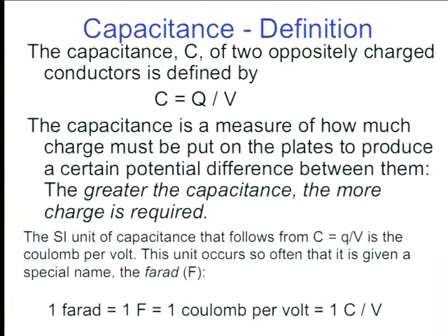So what happens is that if you plot the current, what you really have to do is put a resistor in here to make things act well. The current is going to start at some height, and let's say you have a switch in here, which I will show you in a minute. The current starts, and over a long time, eventually, it's going to go to zero. This is when I close the switch here at t equals 0. So this is the current through the whole circuit.